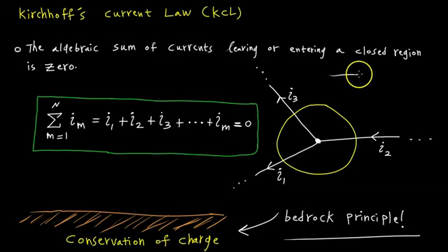Let's just say there's parasitic resistance, some amount of ohms per meter, because that's how you measure the resistance of wires: a certain amount of resistance per unit length. We would draw ideal wires and lump all of the resistance of that entire wire into a resistor, and then treat the rest as ideal. This is a very typical thing we do in electrical engineering and circuit analysis, and it simplifies things and gives you a clear picture of what's going on.